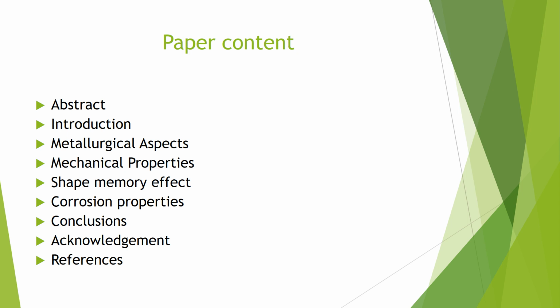So the reader will be able to understand the effect of individual parameters on the weld, and he will have sound knowledge before he starts his project work. For example, I suggested argon is best suited for joining this material. So he need not use a trial and error method to check whether helium or argon is best before starting his research work. He can directly go for argon based upon the previous literature. Those kinds of information we can easily get from this single paper.